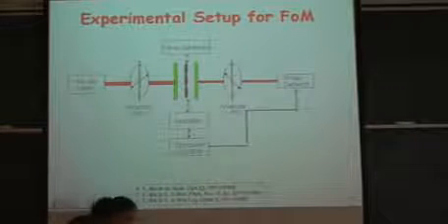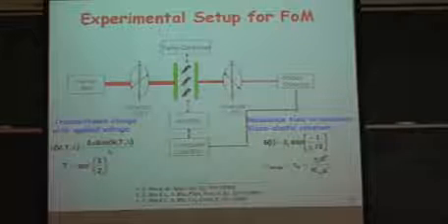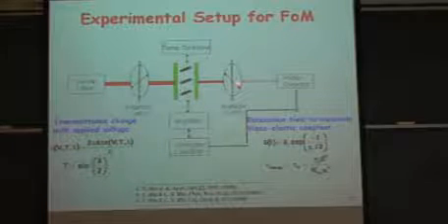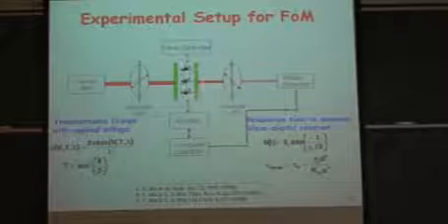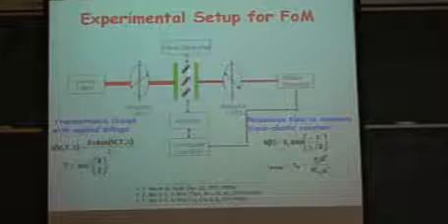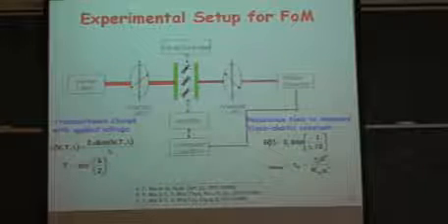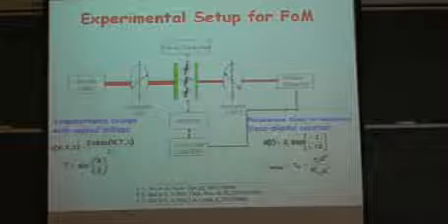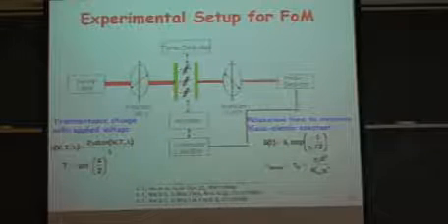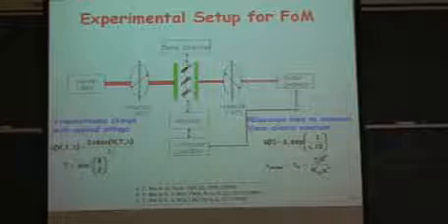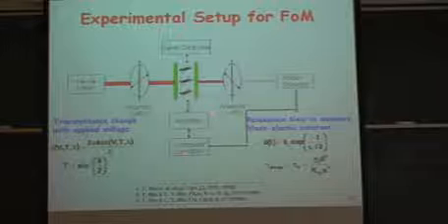Okay, this slide actually shows the same concept: how to measure the birefringence and viscoelastic constant. You see the liquid crystal cell looks like this. Usually the cell gap is 8 micrometers, around 10 micrometers. So it is a glass substrate spin coated with an ITO electrode, and then a polyimide layer.